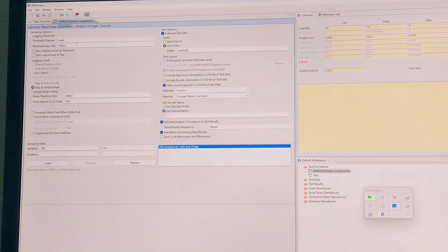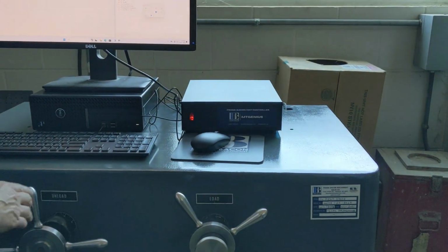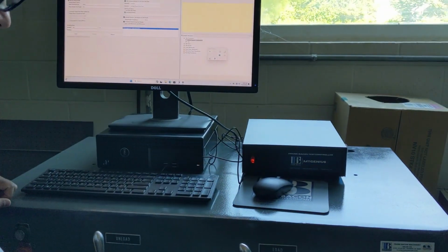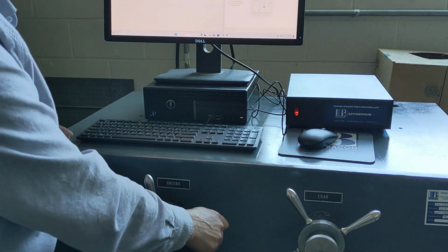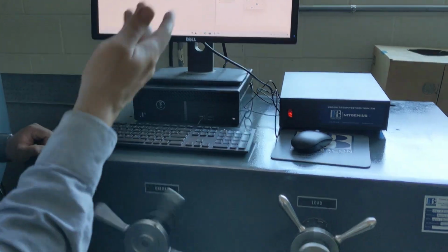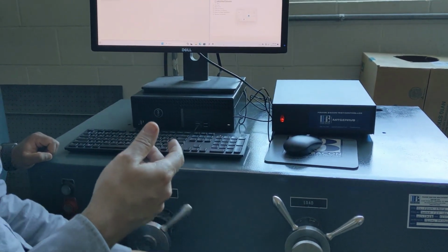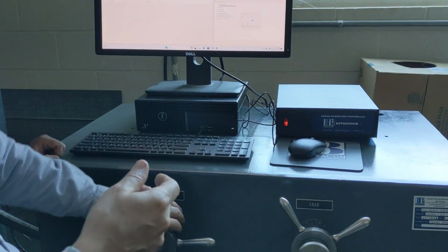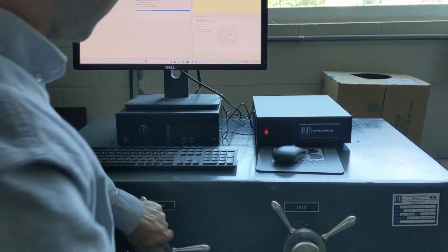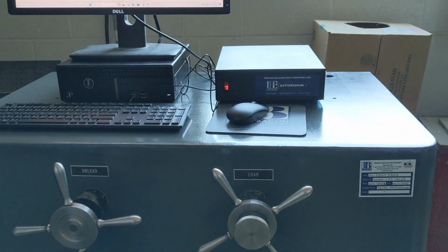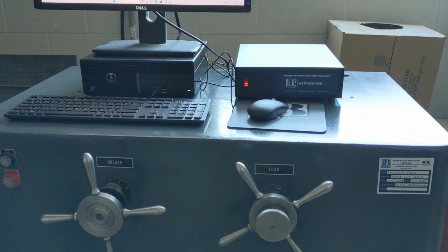You still start your test manually. So that you know, after you load at about 0.5, when it breaks you'll be able to see. All you've got to do is open the unload valve with a very slight unload like this, and let it roll. It's lots of fun. You can unload it. You just have to quickly tap it all the way open.